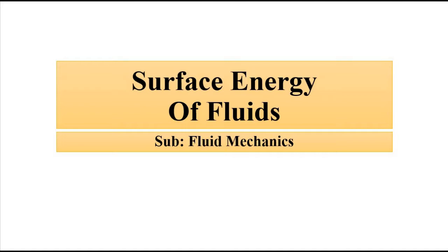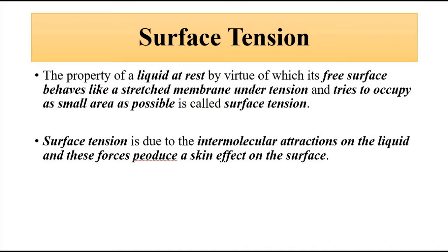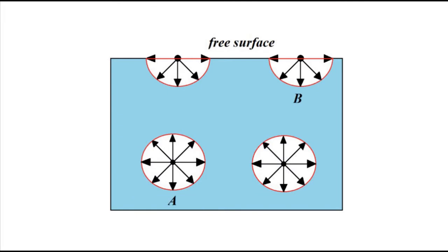Surface tension is basically the phenomenon because of which, for liquids at rest, the top surface of the liquid, because of the cohesive force of attraction between the molecules at the top and the molecules within the liquid in a container, behaves like a stretched membrane and is gradually pulled downwards, thereby causing a reduction in the surface area.